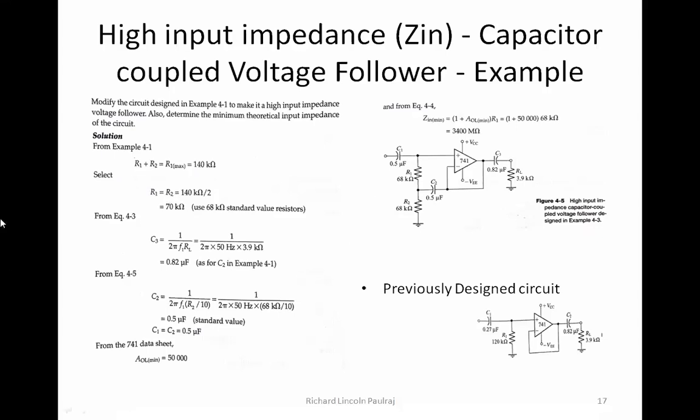So I do not have a separate 70 kilo ohm resistor. As usual, we will be using a 68 kilo ohm resistor. Of course, there's going to be a reduction of 2 kilo ohms. That's the thing about this design. We cannot put the same value of resistors, but if you intend to, then probably you can put another 1 kilo ohm, or probably 1 kilo ohms in series. Then it becomes about 70 kilo ohms. Fine. Now we'll be looking at C3.